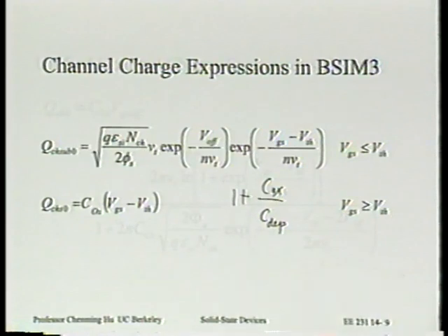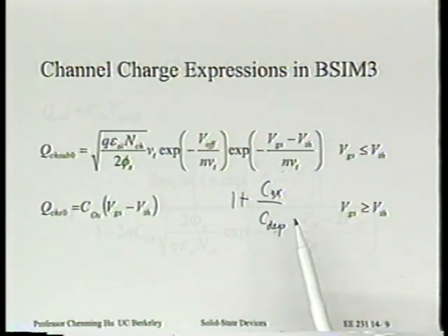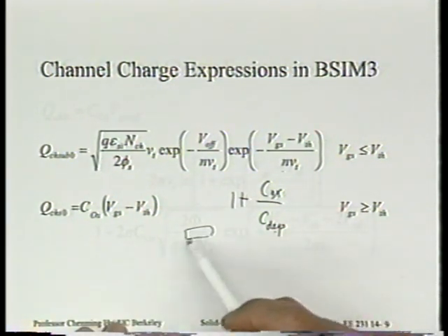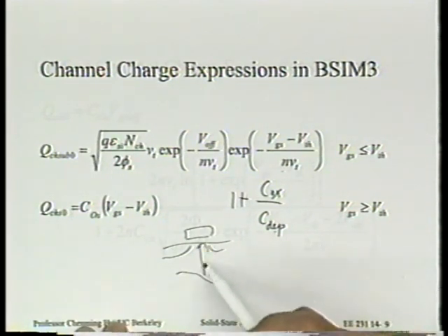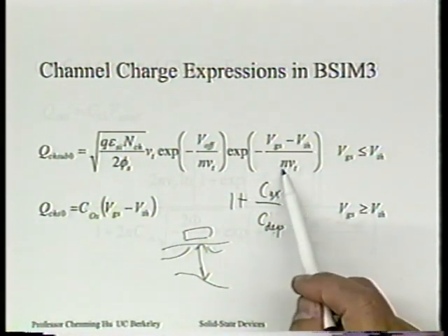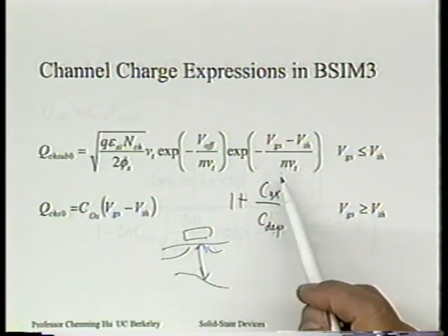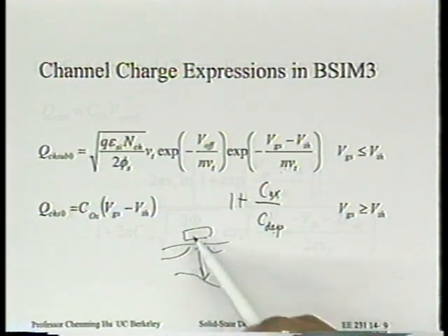Is that right? Yes? But as a SPICE model, do you really want to use the C depletion here? Again, thinking about the geometry, we don't even quite know how deep that depletion region is, right? Should we just use long channel approximation depletion width? Doesn't make sense, right? So why don't we just see what data tells us this n should be? You know what I mean?